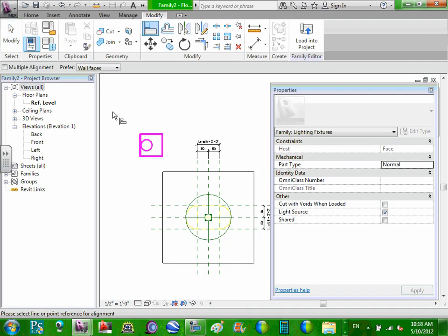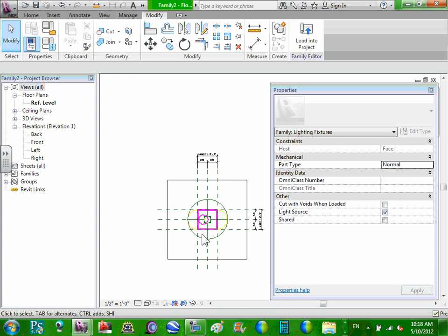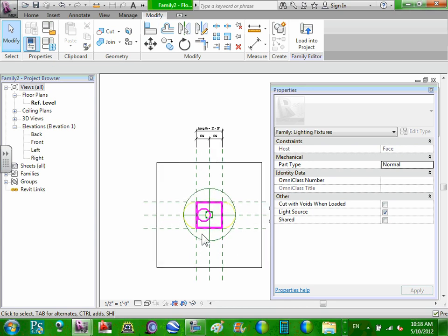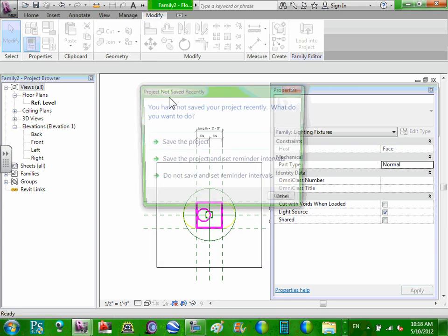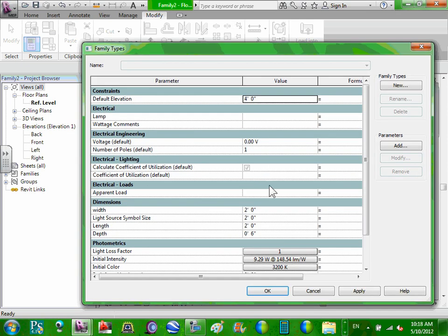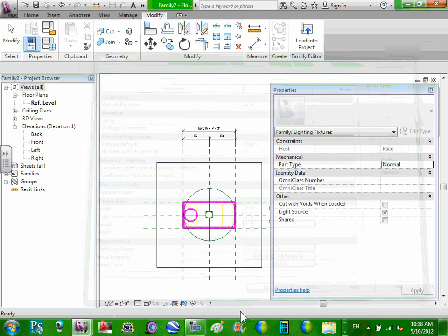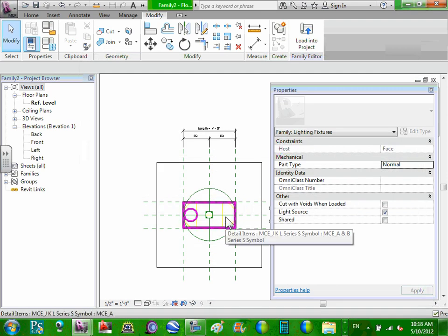The final thing is to align that symbol over the top of this. I grab one end, grab the other end, it snaps over, and I want to lock it. Grab the reference plane I want to align to, grab the symbol, lock it. Now that thing should move with it and grows with the geometry. Right. But it's 2D. 2x4. That's all 2D. Yep.